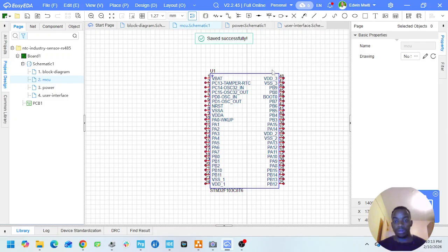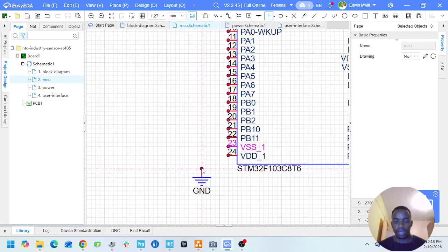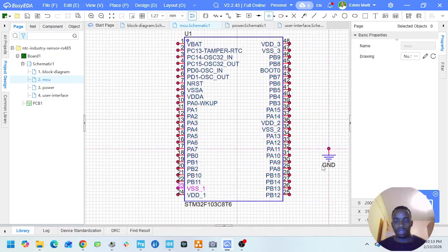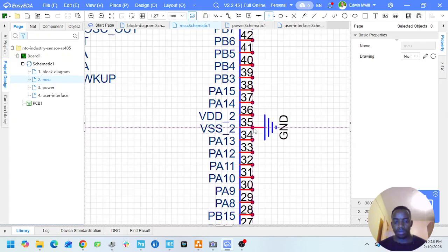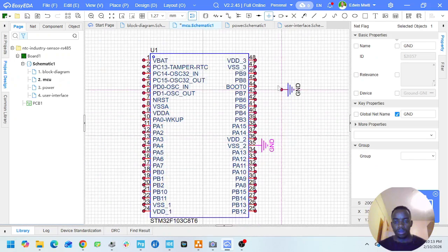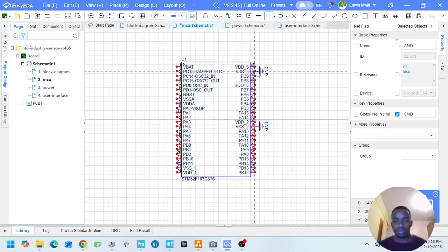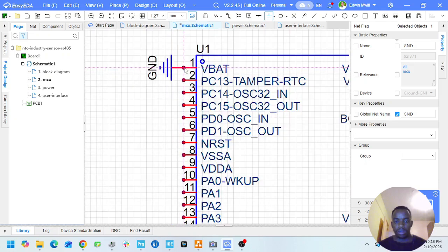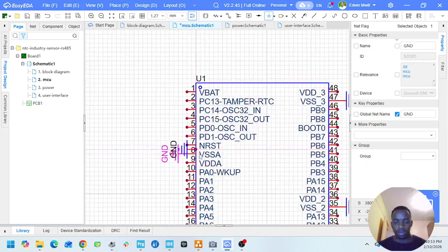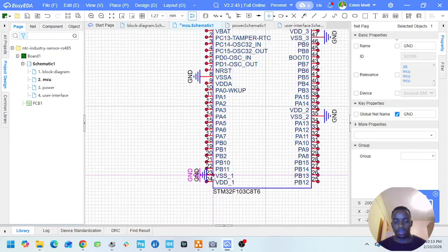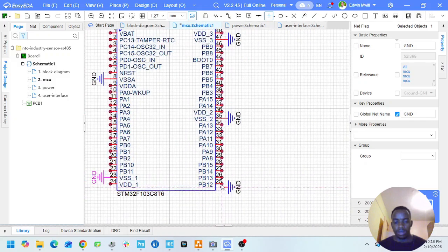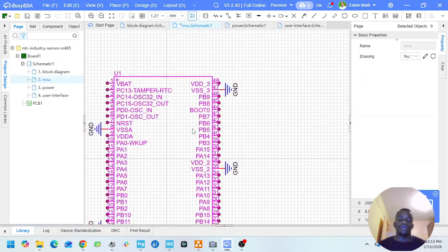So up here on the VCC channel, you click on that and you ground all VSS, right? So this is grounded right there, this is grounded, this is grounded. What else is grounded? This guy is grounded. There's no other VSS. Okay, good.